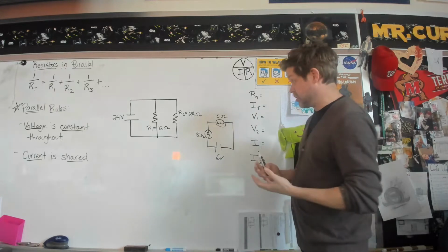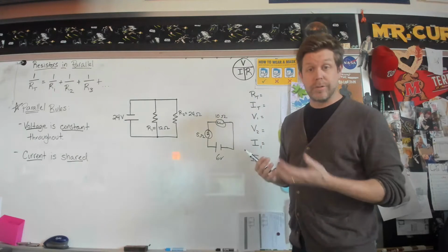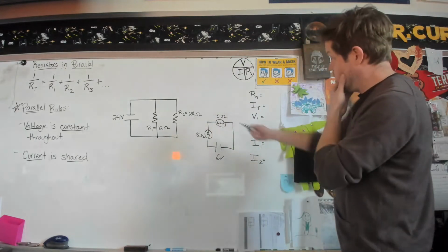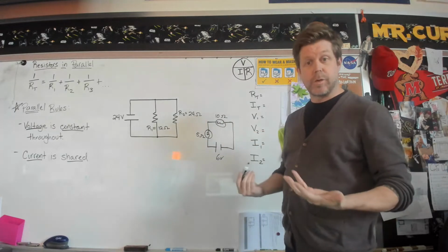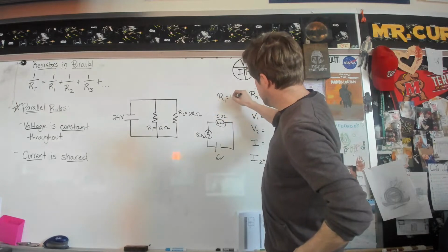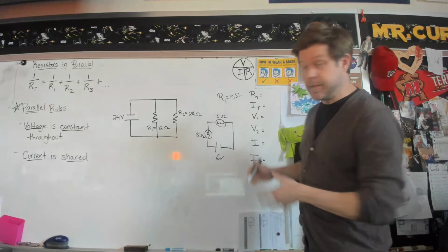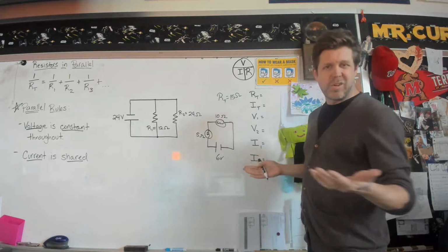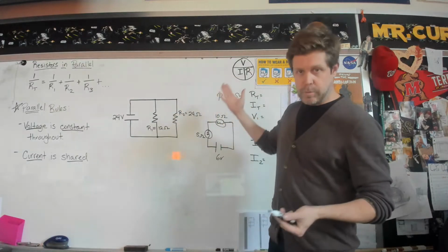We sum those resistors, and that will give us what we call our total resistance or our equivalent resistance. So in this one, I'd have to go through a 5 ohm and a 10 ohm resistor. So I would simply say that my total resistance was 15 ohms. It's nice and easy, worked fine. And then we were able to solve for all of the other parts of the circuit using our understanding of Ohm's law.